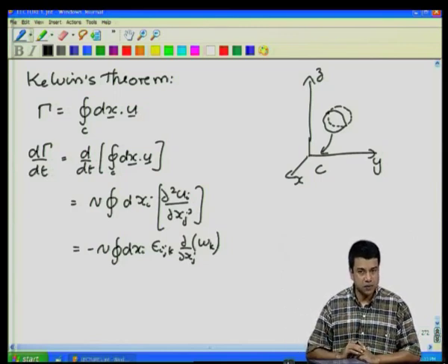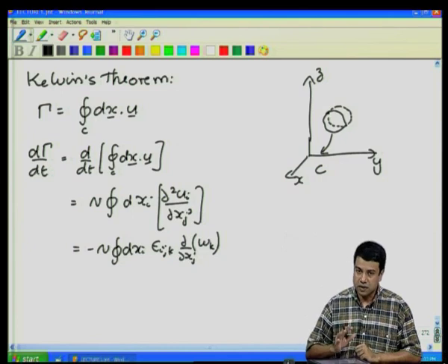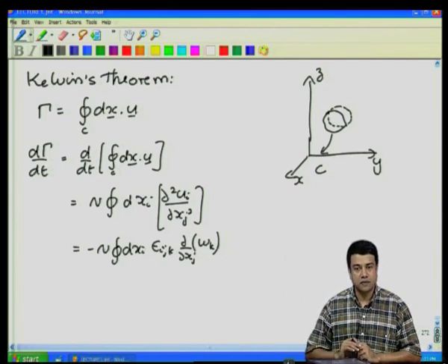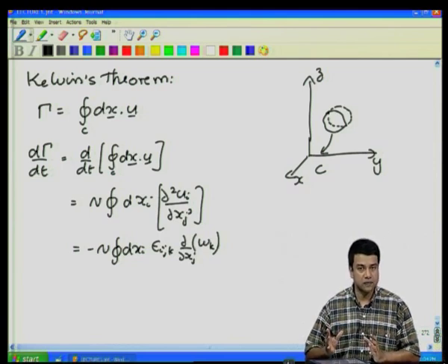That is one reason why we could have talked about potential flows, because you cannot generate vorticity within the flow. Vorticity is transported unchanged through the fluid, and the intensification of vorticity is similar to the intensification of material elements. So, if I had a fluid which was initially irrotational and there was no kinematic viscosity, at later times it has got to continue to be irrotational. There cannot be a source of vorticity within the flow itself.